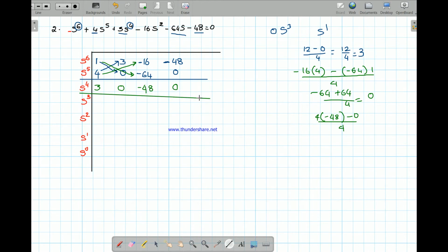So let us go on calculating the next row in the Routh array. This row is over now. Now let me construct this row. Yes, 4 into 0 minus 3 into 0 is 0. 0 divided by 3 is 0. So you are getting this element as 0.